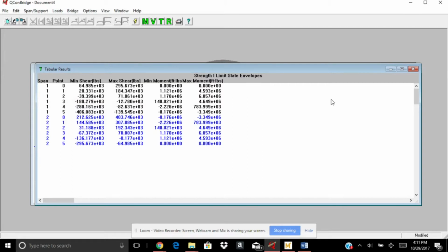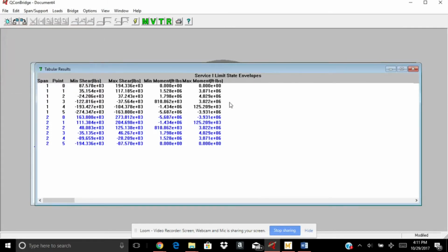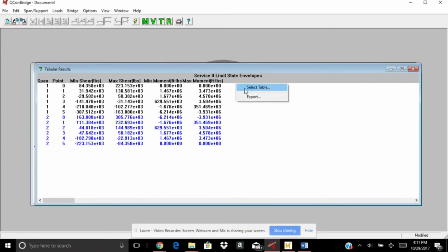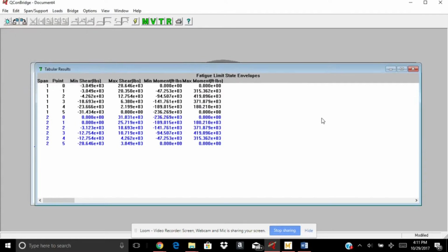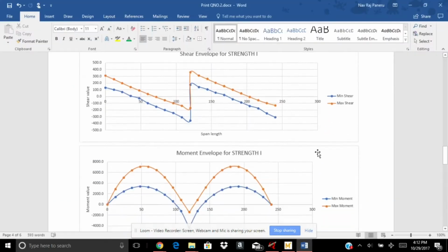And now we are almost done, but before that I'm going to teach you one other method. This other method is even quicker than the one that we just learned. The thing with this method is that if you know the exact area of cross section of the bridge and all of its properties like area, moment of inertia, modulus of elasticity values by yourself, then you don't have to calculate WDC1, WDC2 and DW manually.